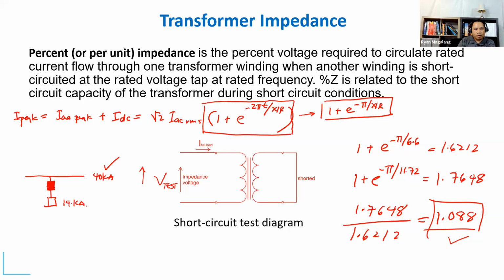There is a published document per manufacturer that will tell you that, let's say, this is an F-frame breaker, and if you wanted to use a fuse upstream and it's a class R fuse, you are allowed to go up to 400 amps. That's your maximum. So there is a table.